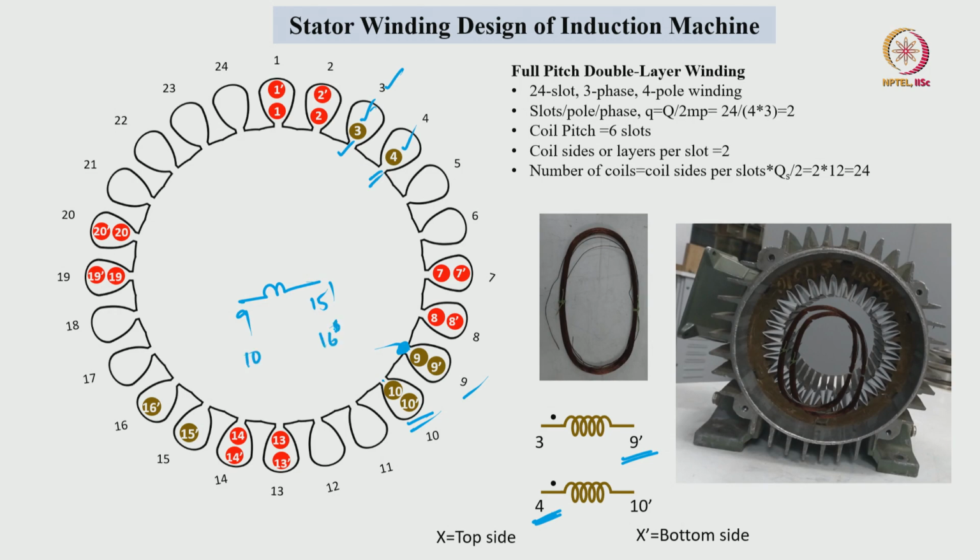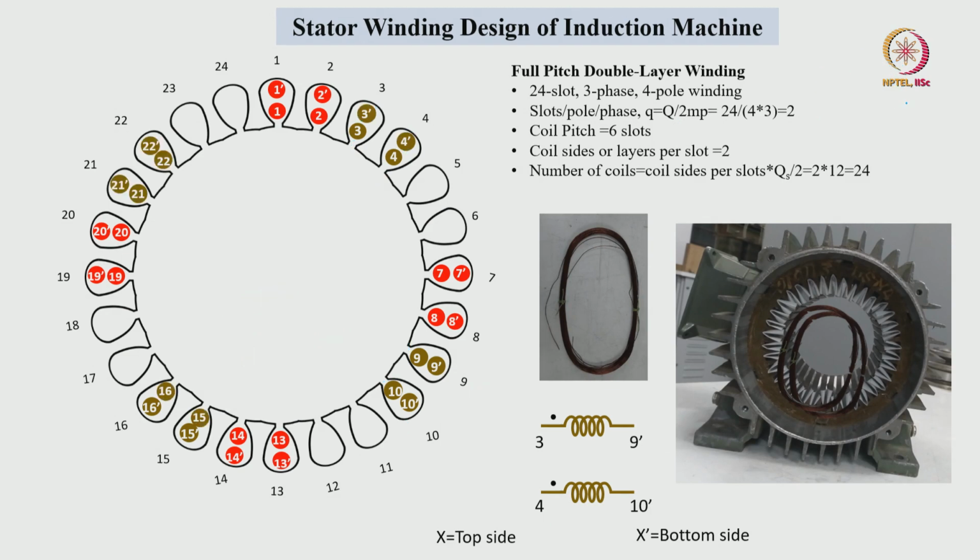Here coil pitch is decided based upon the full pitch winding, 1 plus 6 is equal to 7 and for example 9 plus 6 is equal to 15. So, 9th slot top conductor, that is without any dash, we are placing, the other end is in 15th slot bottom side. So, the remaining coil sides related to the B phase also are placed in the machine. We can see these 4 and these 4, all 8 slots are filled with second phase conductors or second phase 8 coils.